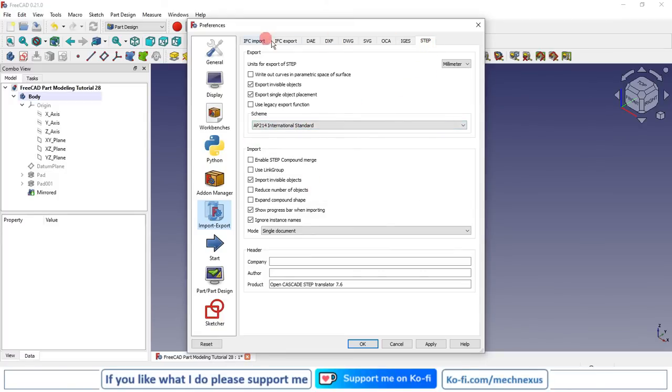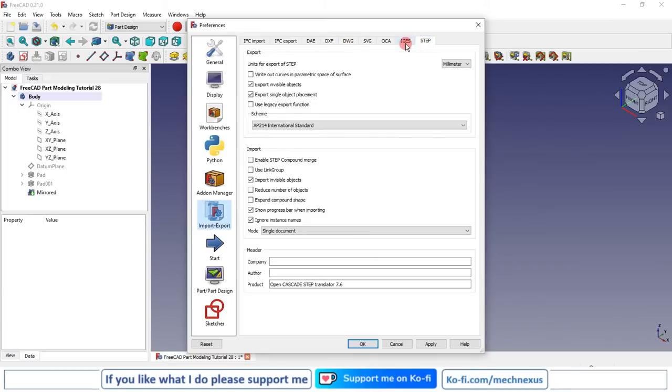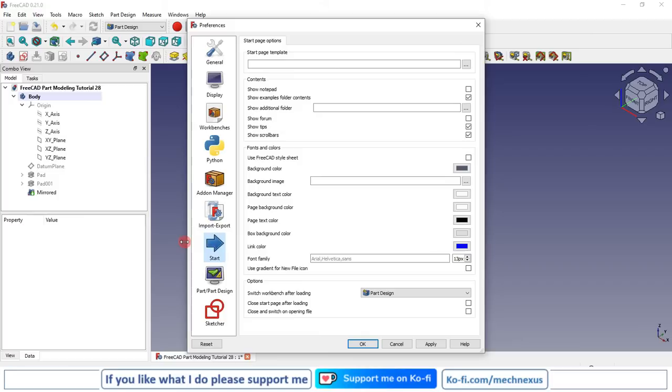So the most common file standards we use are DXF, DWG and IGS and STEP. For 3D it is IGS and STEP, and for the STEP file you can select the schemes available here. So AP214 is the international standard, keep that as default, and then we will go to the start page.